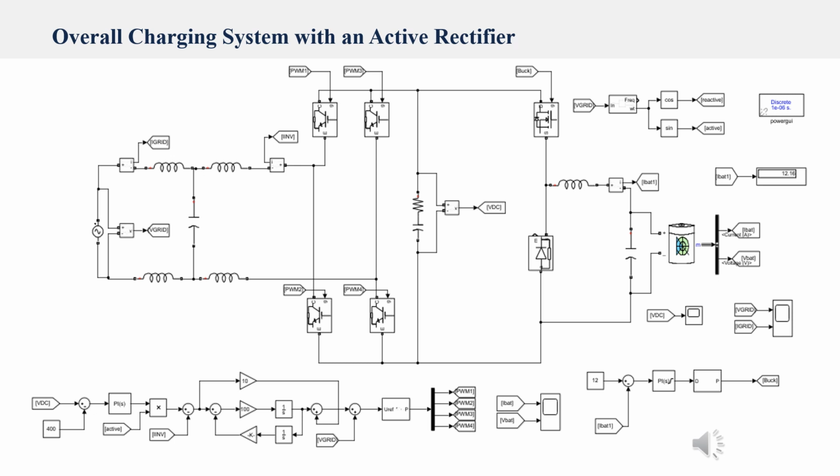So for the charging, we have the buck using a MOSFET, and then this MOSFET is connected to an inductor and then the capacitor, and then it is able to charge our battery. So for the charging operation, there are a few controls which we will delve into further to see how it does the control to charge the battery.